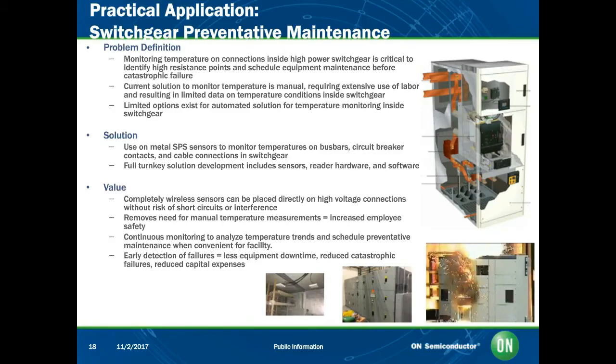So the issue historically is if these connections become degraded, if they get corroded, or if they're bolted together and they're not torqued quite correctly, that results in a high resistance connection. And as any electrical engineers out there will know, as you run more current through a higher resistance, you burn more power, which translates to heat. So facilities engineers really want to understand what the temperatures are of their bus bars.